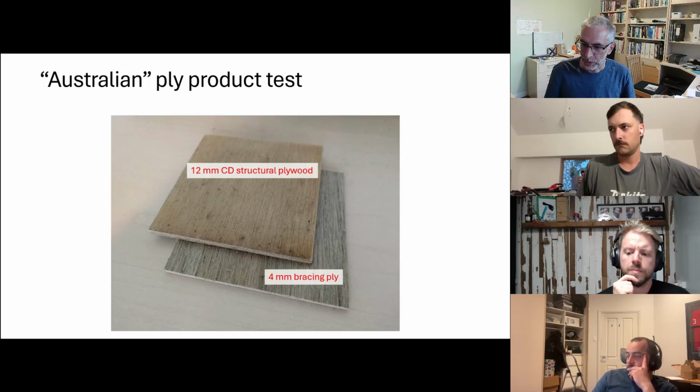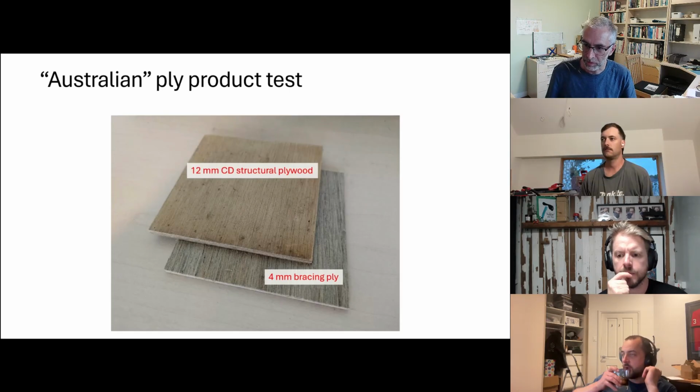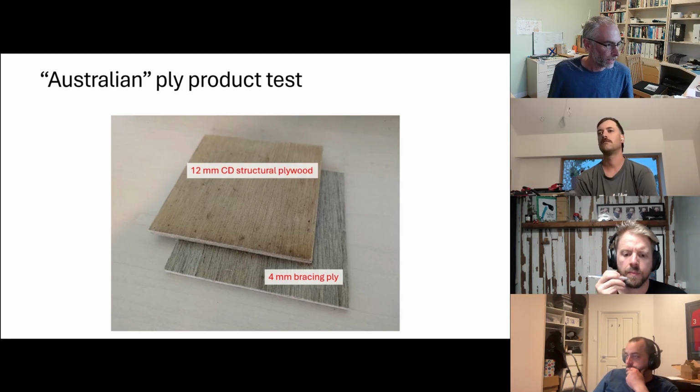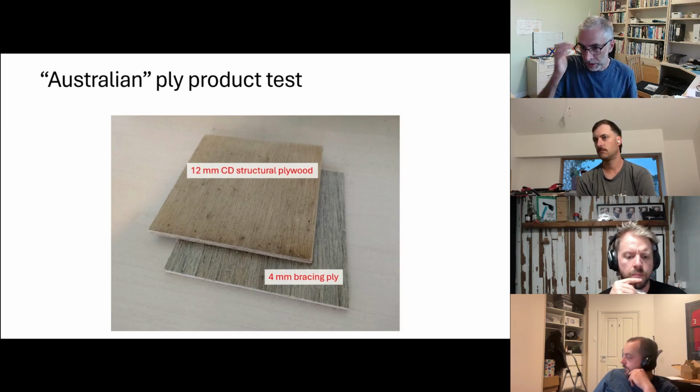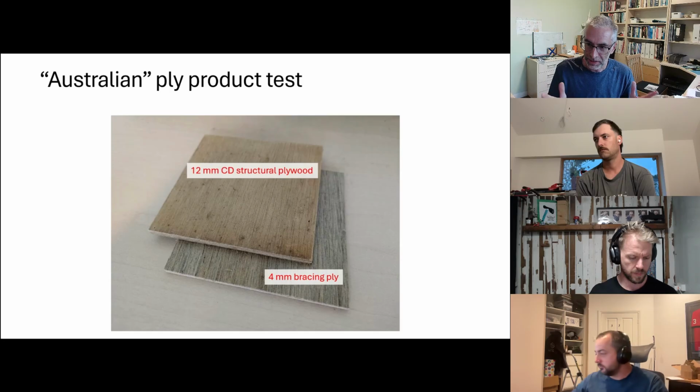So my first point is your Australian ply that you bought from your hardware supplier is not necessarily Australian at all. So this is a global industry. So let's test those. So what you can do, you can get an ASTM E96 test done, and it costs, get this, $200 to do it. So it's not a very cost prohibitive exercise.